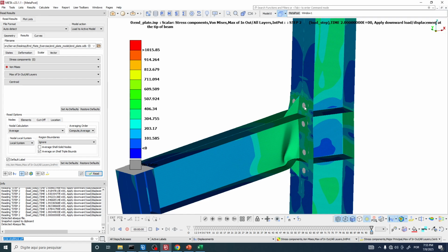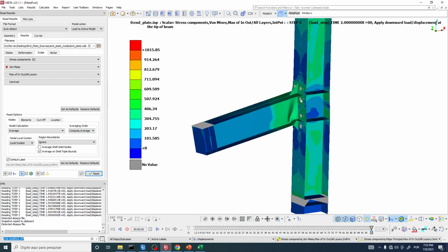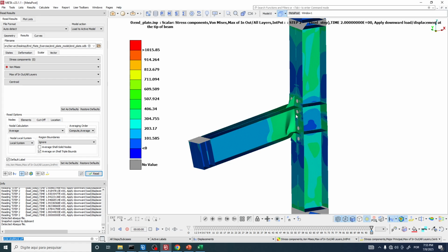By the way, there is one really important thing that we should do, which is to verify that we have solved the mathematical model correctly. So we need to, for example, verify that we have equilibrium in this structure, meaning that the sum of all forces in all directions is equal to 0. I can't forget to do this in the next video. This is part of the post-processing.